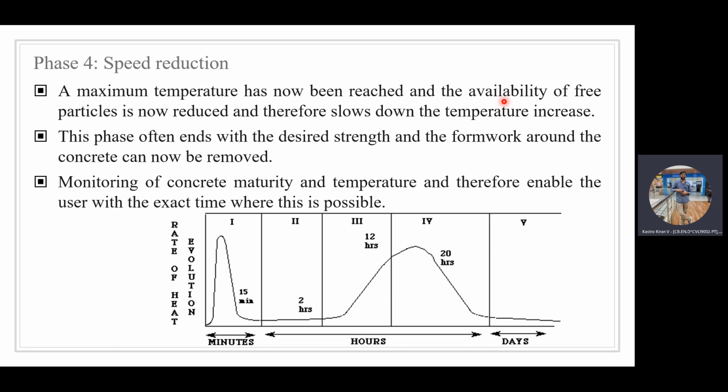And whatever the availability of free particles that are there, all those free particles are completely mixed with the water. Now, does the water have any cement compounds to react with? No, there won't be any cement particles where water can react. So because of this, what happens? Since there is no availability of cement particles, water cannot react with any other cement particles, because all the cement particles have completely reacted with water in the first 3 phases itself.